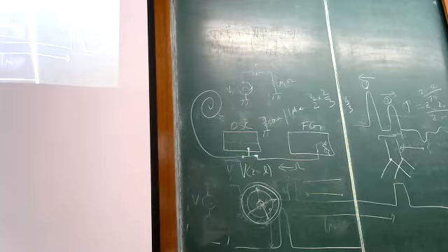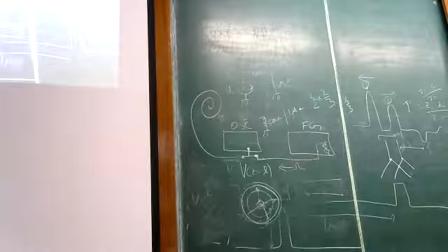So the BNC cables, the fat ones, are usually spec'd only to work till about 1 gigahertz. Basically, beyond that, it's not guaranteed that the property as a function of frequency will remain flat, so your pulses will distort, will get attenuation and things like that. Whereas these kinds of coaxial cables can go up to 60 gigahertz or so.